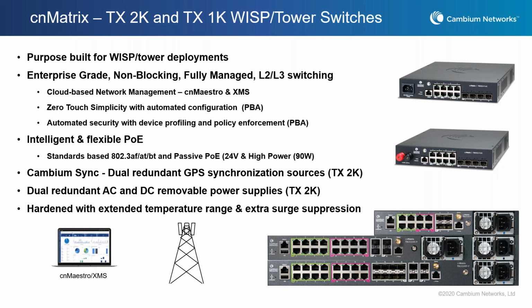So in the enterprise space, PoE obviously is very, very common, very popular, but it's all standards based. 802.3 af, at, bt, it's all standards based. In the WISP deployments, there's a lot of devices out there that use non-standard or passive PoE, either 24 volt or 54 volt. And these switches inherently support those modes as well, so you don't need special power injectors and so on.